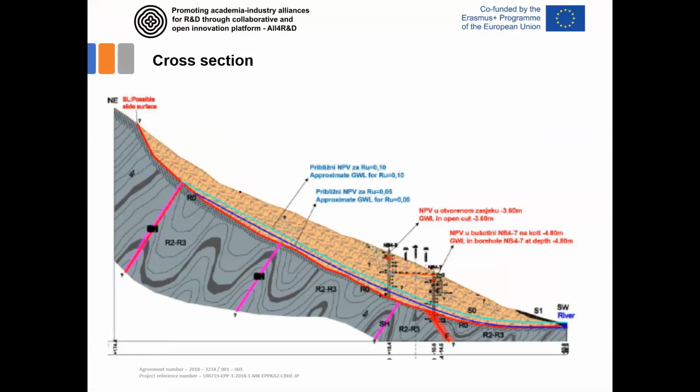If you install the inclinometer here, you will measure the horizontal displacement along the depth. You're expecting to have horizontal displacement here, and then suddenly to stop having it here, since this is stiff rock. When you draw it, it looks like this. If you get back in 1 year, you may get this. In 2 years, you may get this. So displacements are going more and more horizontal.